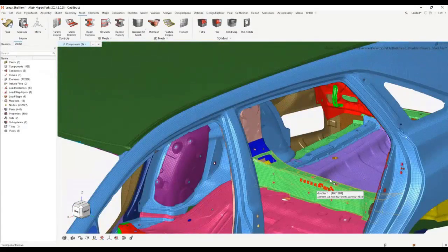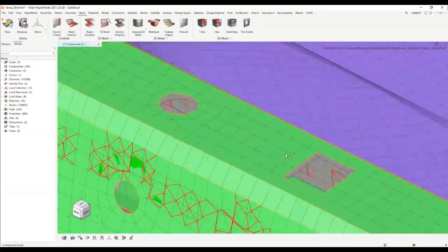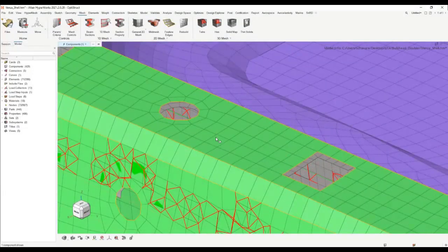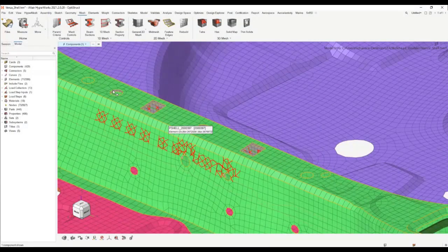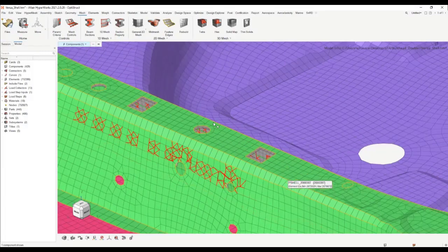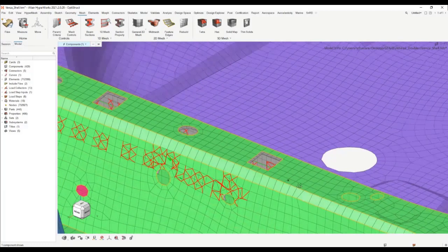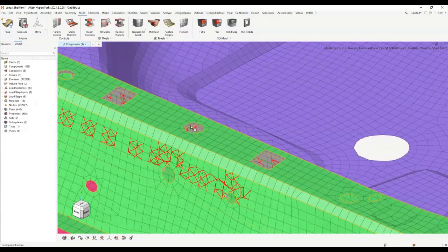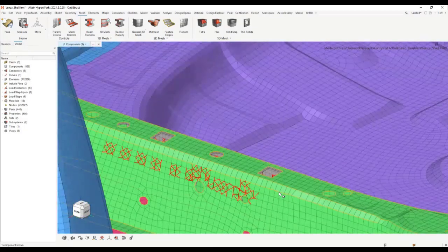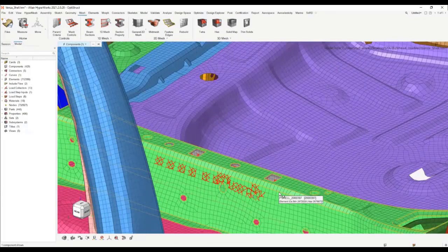And this particular doubler looks at your parent surface, and if it has any holes or any access hole, it maintains those holes and access areas as well. So it's not like if you have an access hole on your parent part, you're going to lose that with the doubler. This workflow takes care of the underneath mesh below it.